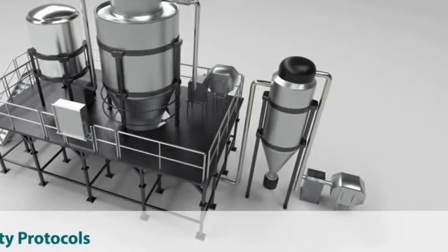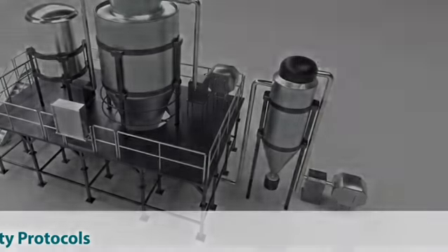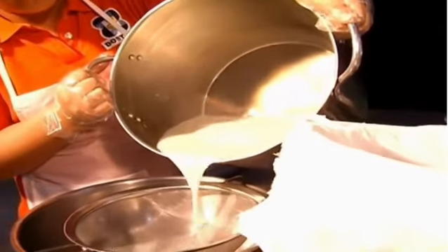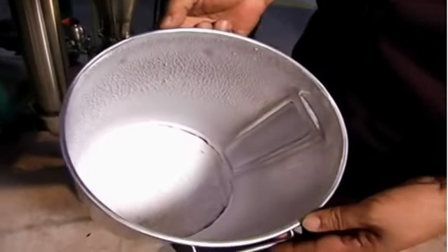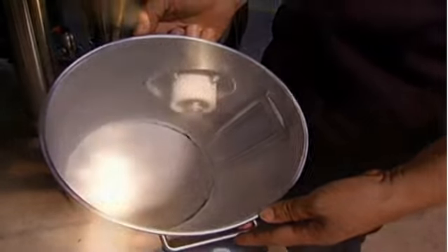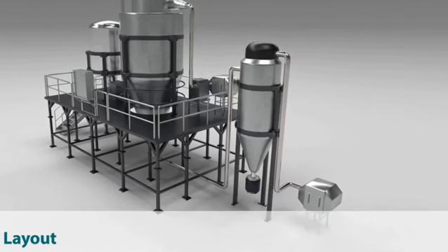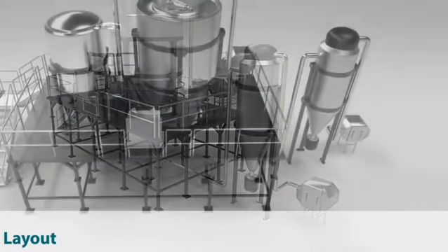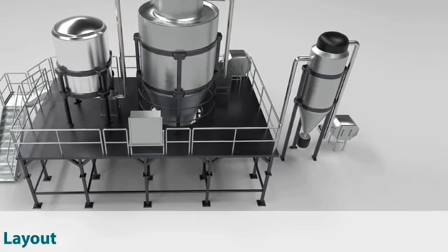Spray drying can be done in different ways depending on the product. In co-current drying, the liquid and hot air flow in the same direction, allowing rapid drying and protecting heat-sensitive nutrients. In counter-current drying, the liquid enters from the top and hot air from the bottom, which allows better heat transfer but requires careful control. Mixed flow drying combines these approaches for optimal drying of specific products.